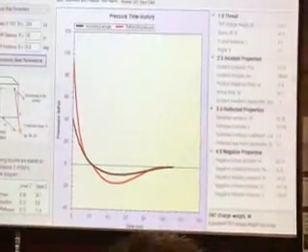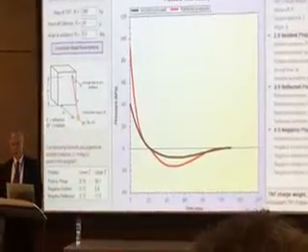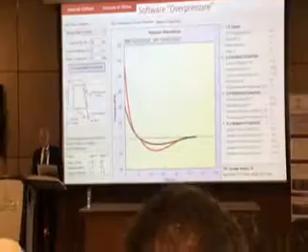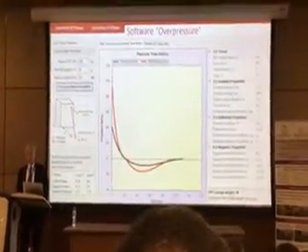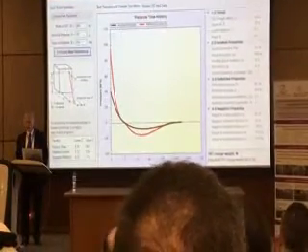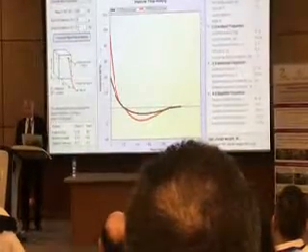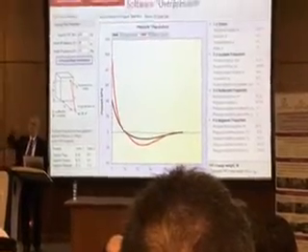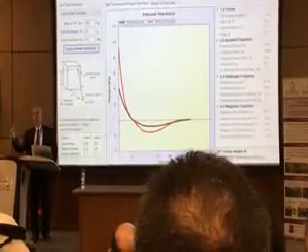So now on the right hand side, you come up with incident pressure, which shows 41 kilopascals, and then impulse is 338, which is the area under that black curve, and then reflected pressure is indicated with the red curve, and here you have increased values, 93 and 570. So if you have the area, you have the pressure, you set that equal to triangular area, solve for duration, you have all the parameters.